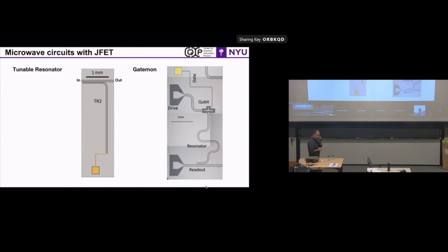So now you can think of two obvious cases. If the junction is open, I have basically an open-to-open resonator. And if it's short, basically I'm shorting to ground. So I can go from lambda over 2 to lambda over 4. That's the minimum. But then I can also think of a circuit that has an inductance here that I can change. So I will talk about that very quickly.